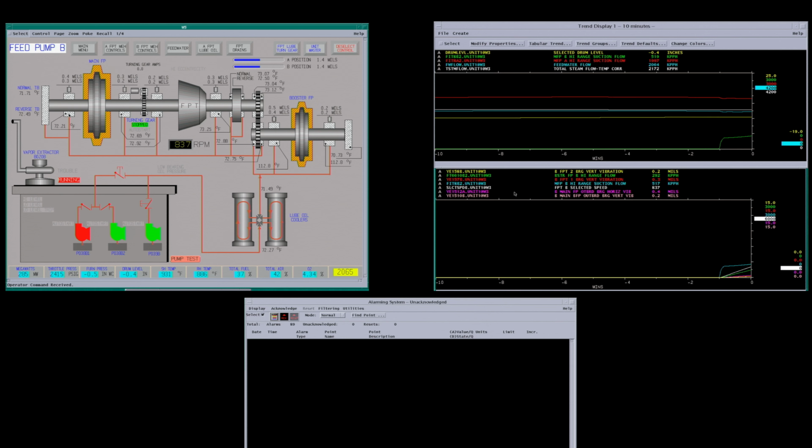These pumps got started and stopped quite a lot because once you came below 270 megawatts, you had to take a feed pump off. And if you got above 290, you'd put another feed pump on. The actual size of the feed pump turbine was fairly small. They're pretty durable little turbines. I'd say it put out about 10,000 horsepower. We had about 150 pound steam off the IP turbine and then exhausted down to the main condenser. So it had gland steam on it.